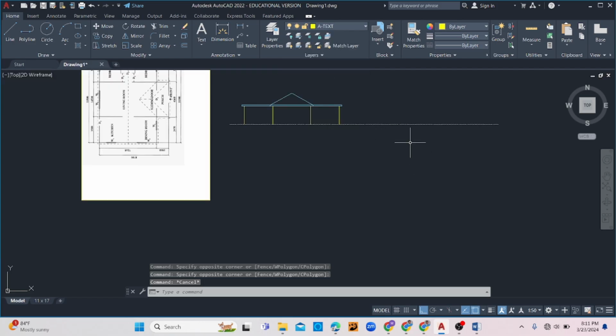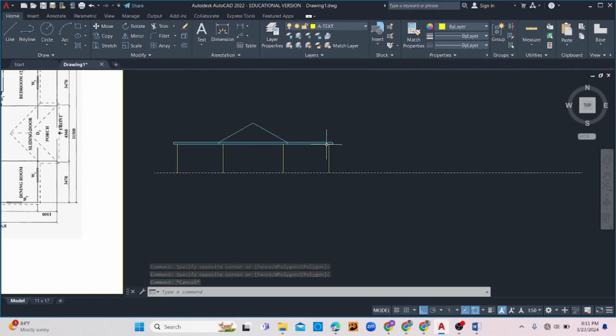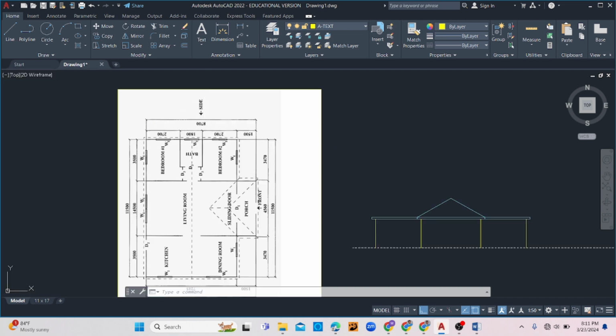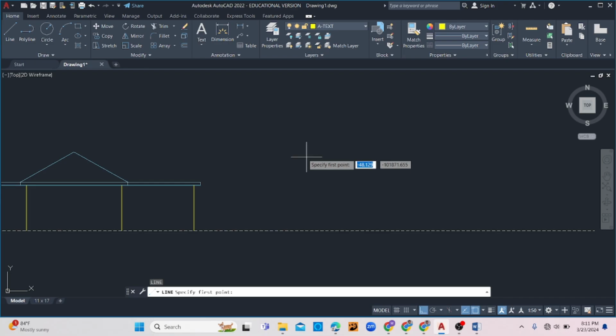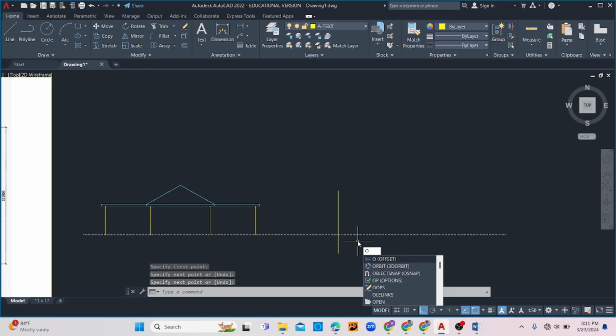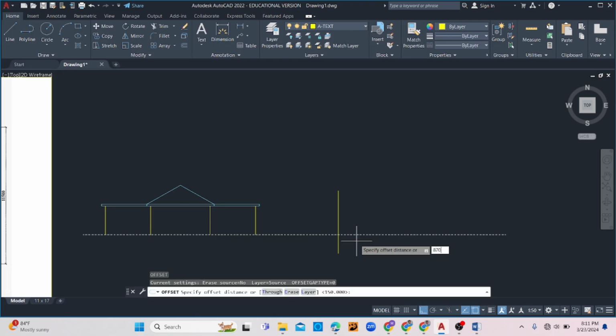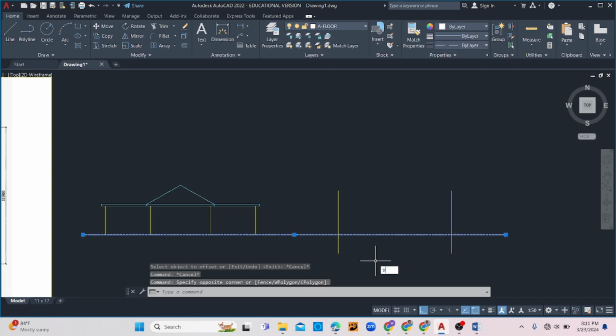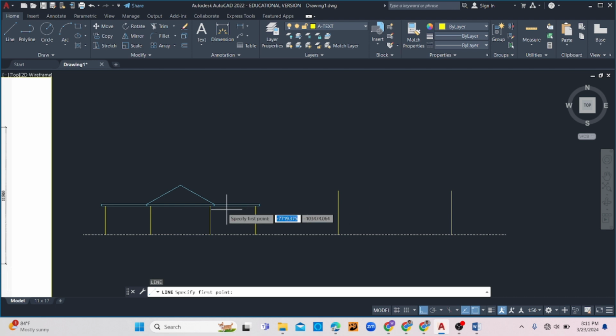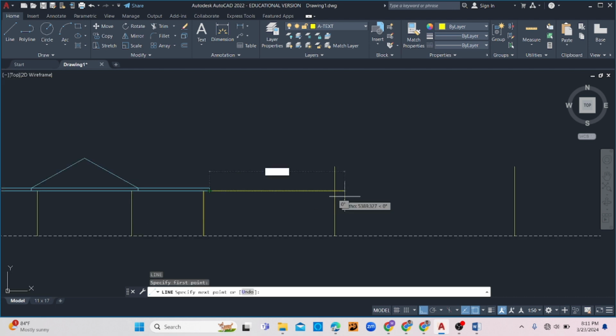Now I'm going to start the other end of the drawing, the side view basically over here. The measurement is clear, as they tell you that it is 8,700. So I'm just going to draw a vertical line down somewhere here, and then offset it 8,700 to my right, like this. I'll clean up my drawing by trimming, filleting, whatever technique you want to use. I'll use the drawing to my right to determine the height of my roof.